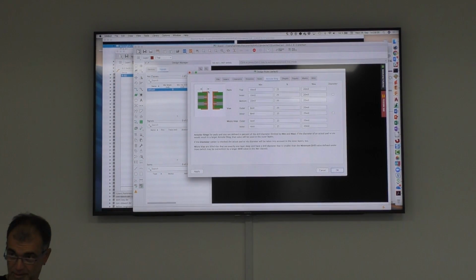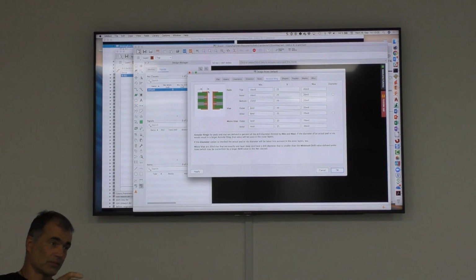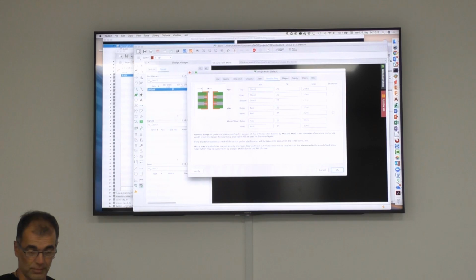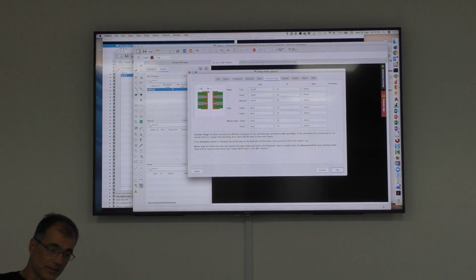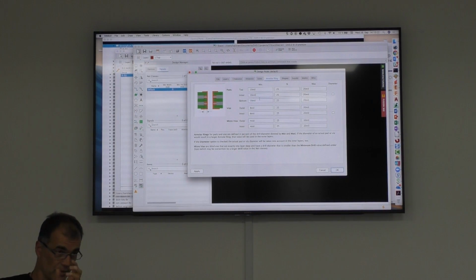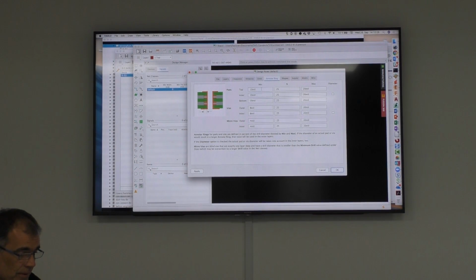That's what I didn't explain to you, but of course I can, because if you have a through-hole component, you need a certain diameter for the drill, let's say 0.8 millimeters or 1 millimeter, depending. And of course I need some copper around this for soldering. And this here is the way how it is calculated. Let's say we have 1 millimeter. If you go there, pads on top here, I have a 1 millimeter drill, and they say the annular ring is 25% of the diameter, a quarter of a millimeter, 0.25 millimeters. And now I can have some minimum and maximum values.